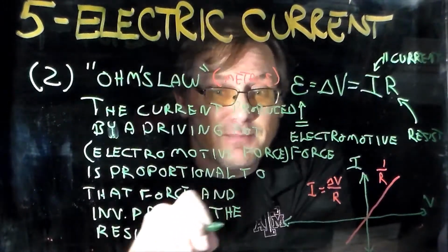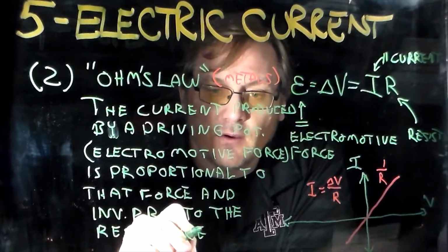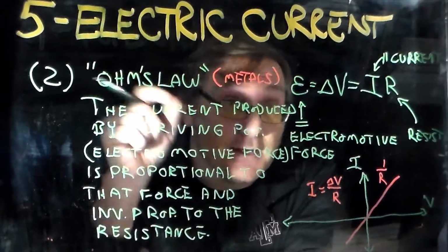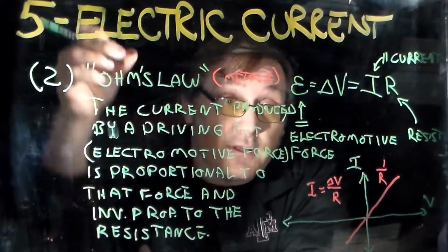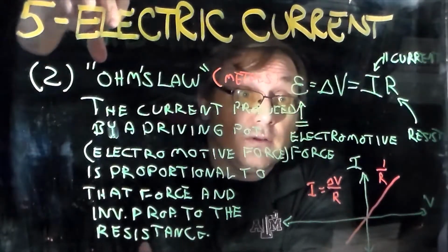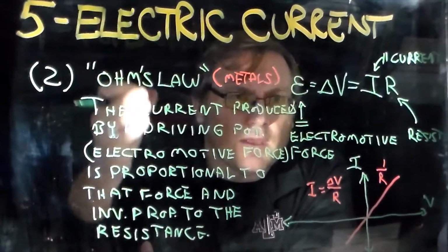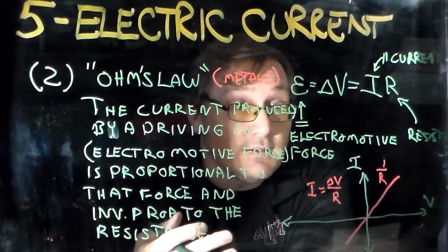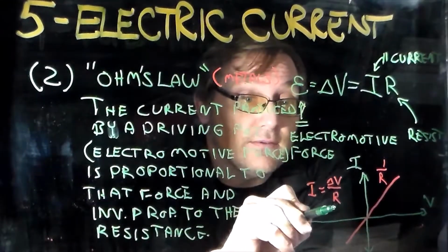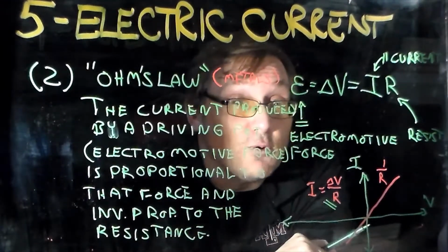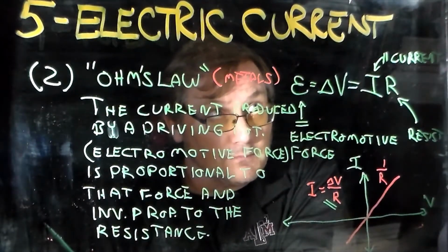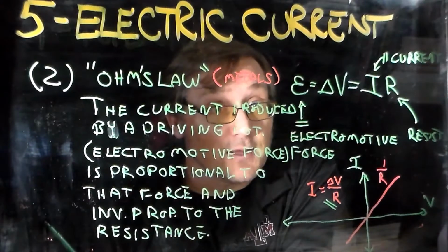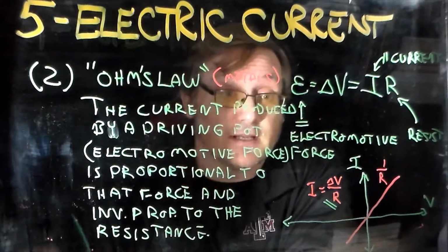And this might, if you're paying attention, remind you of what happens in a fluid. If you were to take a big pipe and drop a ball in through some fluid, it will reach a steady velocity, and you'd have a resistance to that motion based on the drag coefficient. So the higher the drag coefficient, the lower that velocity is.